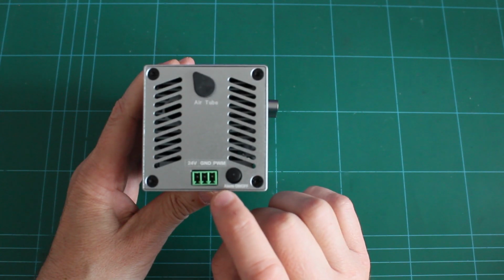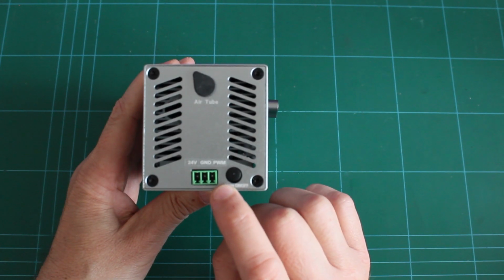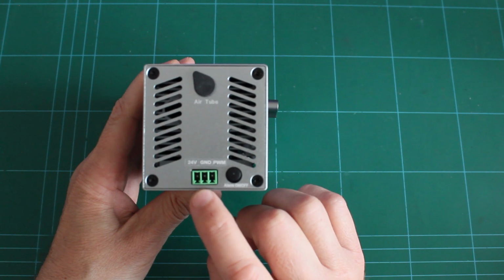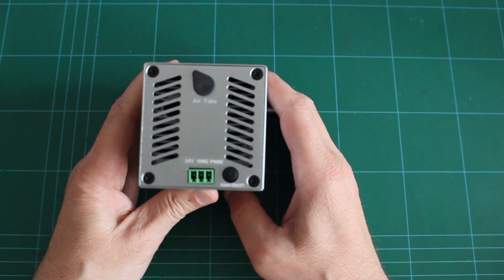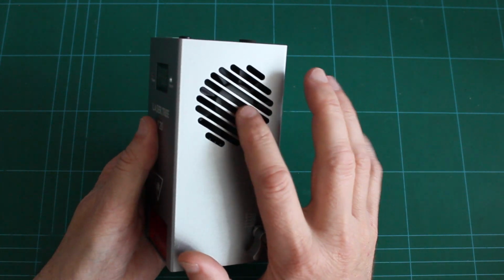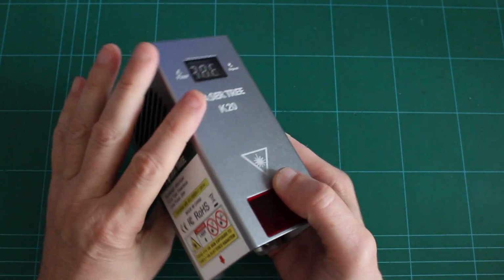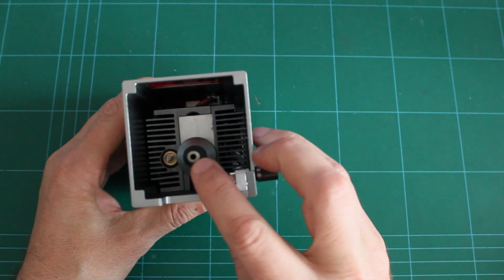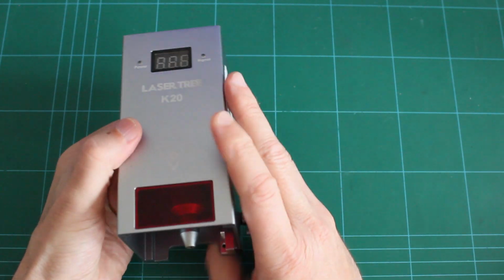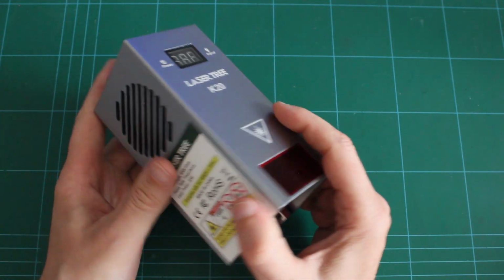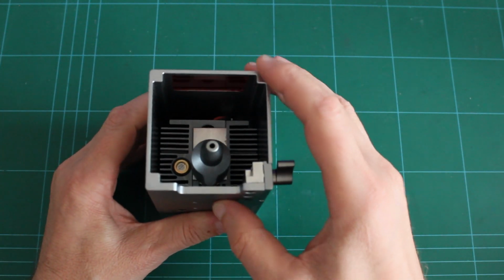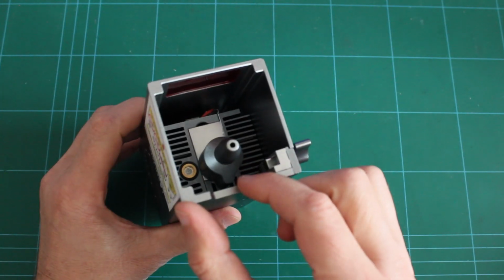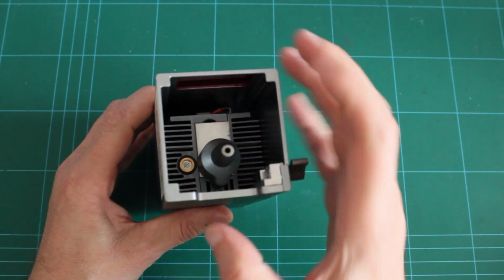The control PWM signal is supplied to the third pin, the second pin is common ground, and the first pin supplies the 24-volt DC for the laser. 2 built-in fans are used to cool the laserhead and the cutting zone and to remove gases from the cutting zone. The laser source is mechanically protected by the laser's housing, and that makes it difficult to estimate the laser beam's position before the start of cutting.